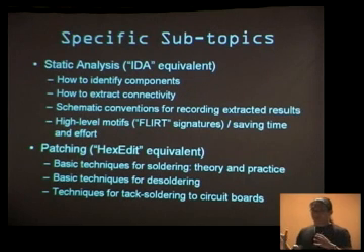I'm going to pare down the talk a bit and talk about specific subtopics aimed toward people who are less familiar with hardware. I'm going to be looking at a lot of the static analysis, the quote-unquote IDA equivalent: how to identify components on a motherboard or circuit board, how to extract the connectivity, how to draw schematics, and the conventions for recording the extracted results. And some high-level motifs, kind of like the FLIRT signatures you might apply to a Win32 library to help you save time and effort. And I'll go through some basic patching techniques.